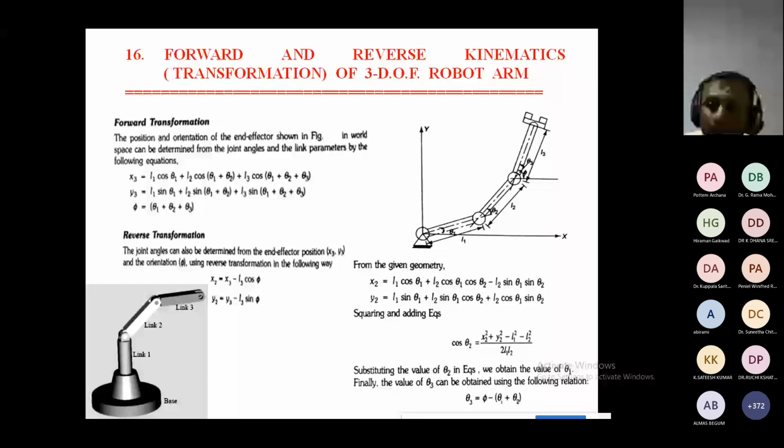First we are doing these things as a trial, for the simulation, through either MATLAB or the free open software Scilab. The link lengths are considered as per the design. Then after the motion we are allowing theta 1, theta 2, theta 3. After calculation, we have to check whether that will be equal to theta or not. If it is not theta, then the simulation model is wrong. Then it must come to theta.